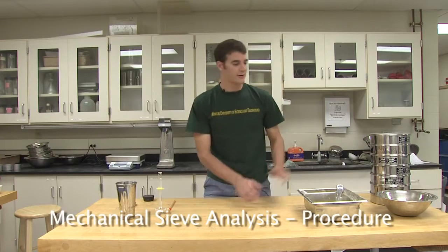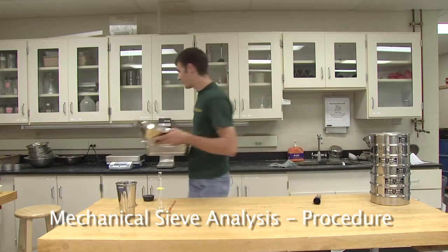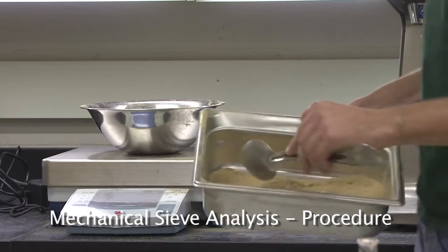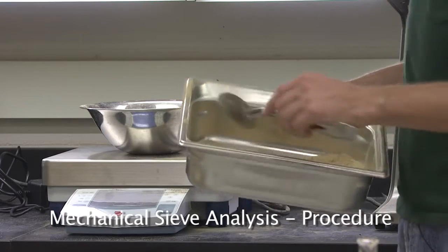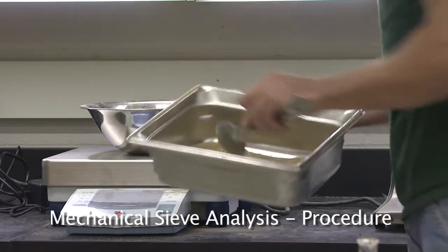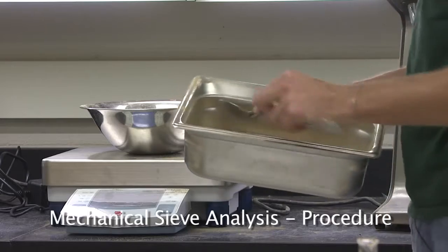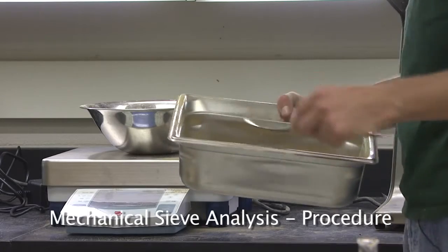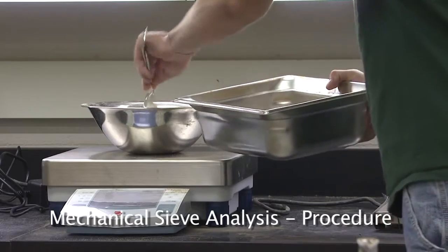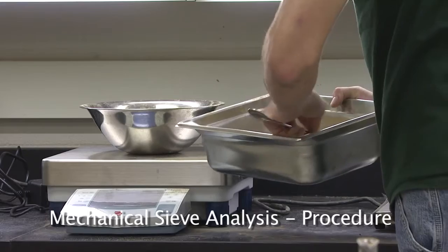Start by weighing out a 500 gram sample of the provided air-dry soil. It is important to mix the sample in between each scoop so that the 500 gram sample of soil is an accurate representation of the provided soil sample. Record the total mass on the data sheet.